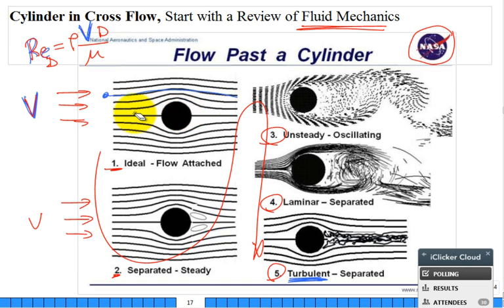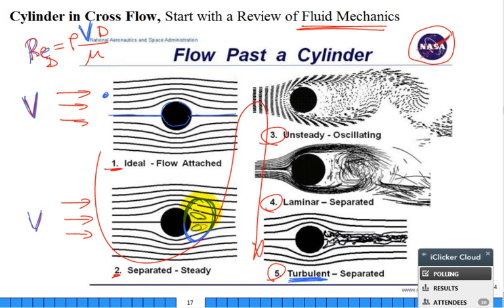And they have this one case right in the middle. It kind of hits and splits, joins and goes back. Okay, what happens here is the velocity goes up. Well, what do you get in the backside? Isn't this the backside in here? What's happening? You're getting some recirculation. So the fluid stayed pretty well attached and then got back together on the backside of case 1, but on case 2, no. It leaves the surface right here and then gets back into where it needs to be. But in here, you have fluid circulating.